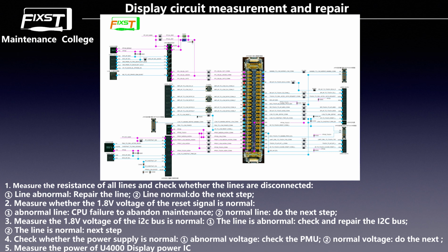When you get the phone, you confirm that it can power on and the screen is black. First, we need to change the LCD to test it. If after changing the LCD it works, it means the LCD had some problem, and we just change the LCD, right? But if after we change the LCD to test, it still does not work, it means the motherboard has some problem.